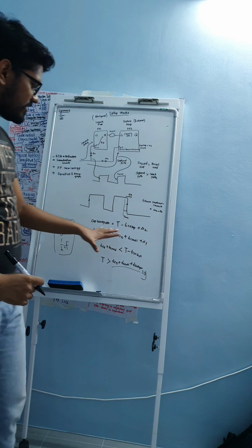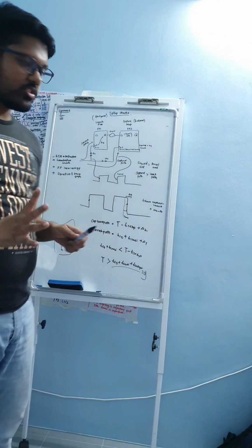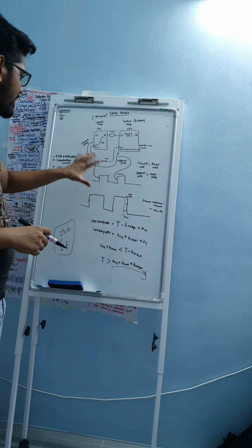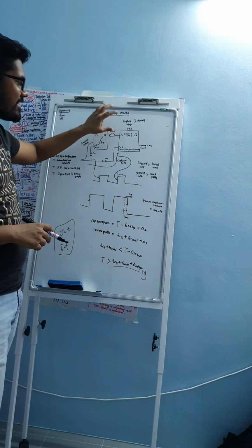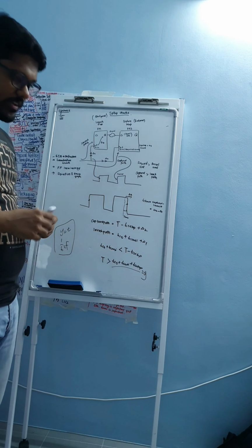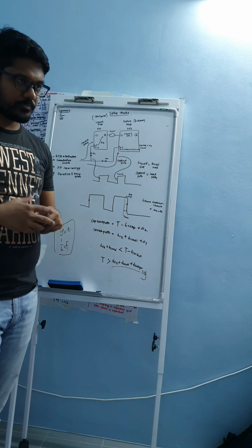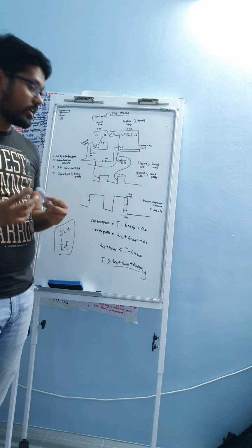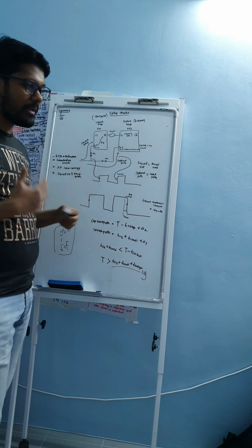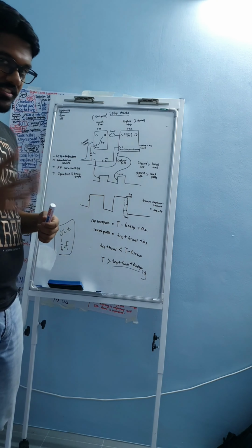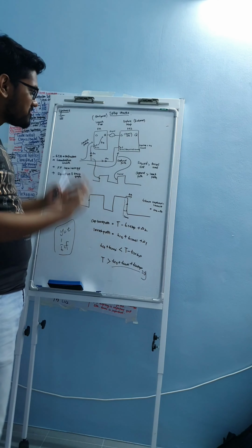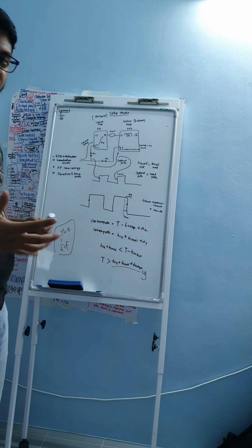So actually introducing delta is very good in setup because it is delaying your clock and making sure your data path is reaching earlier than it. That's the reason in CTS we have the useful skew command. This useful skew introduces a lot of delay at the clock path to make sure that you meet your setup check. So that is the main reason they are doing that useful skew.